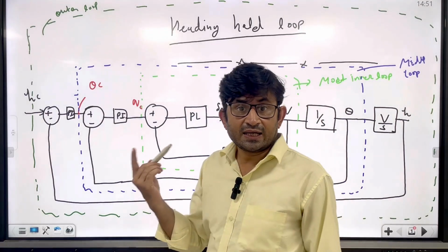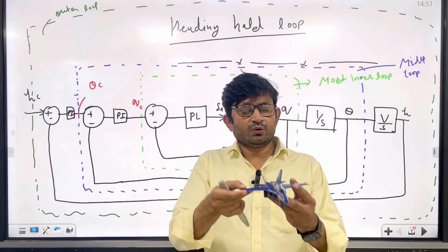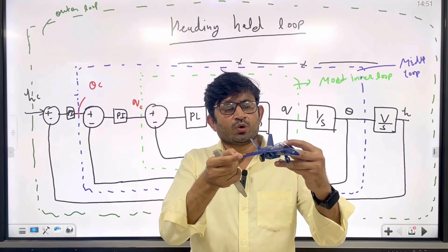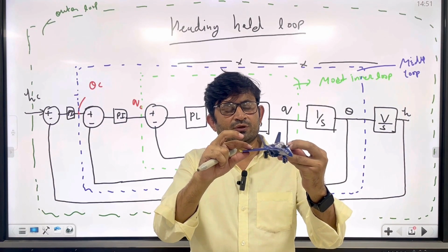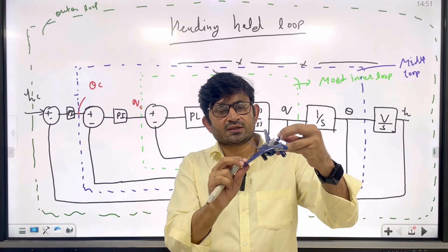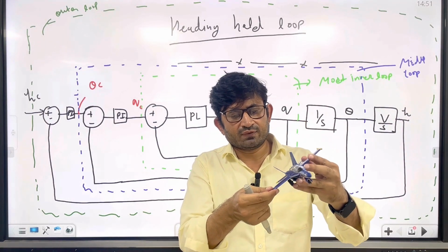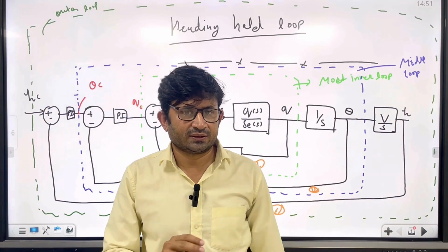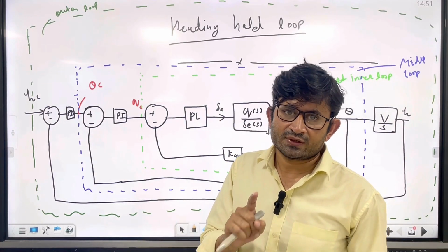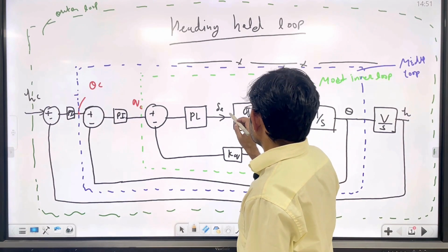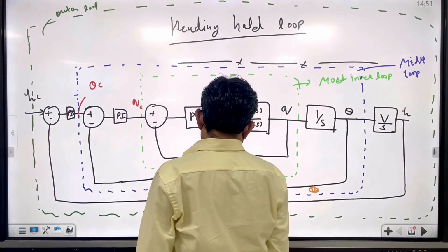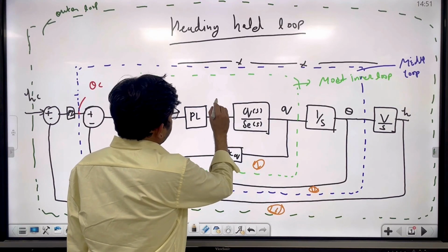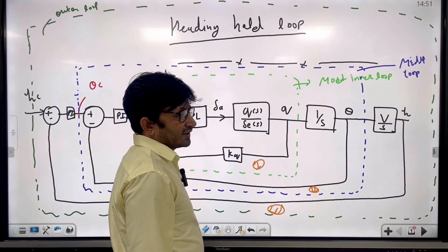In the lateral case, for example, when you deflect the aileron, this down, this up, there will be more lift here and less lift here. So L plus delta L, N minus delta N. This is how we will roll, and then the centripetal force L sin phi will rotate the aircraft in a circular path. So first you are going to deflect the aileron. Here I am going to replace delta E by delta A.